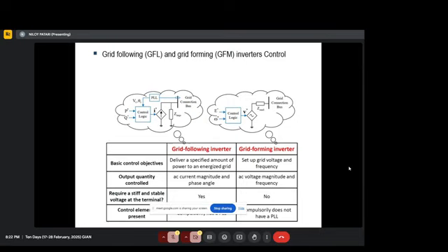and that's how it is injecting active or reactive power to the grid. Grid forming inverters are a bit different. Grid forming inverters act like a synchronous machine, right? They have the ability to control frequency or control active power flows in the system. They can stabilize the frequency, or under resiliency conditions, when the grid is off or a certain section of the network is not connected, they can take care of the grid, the frequency and everything.